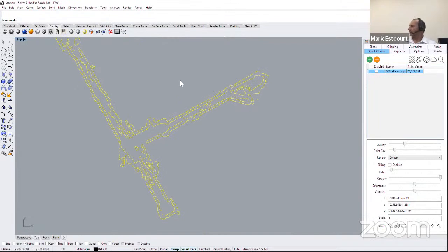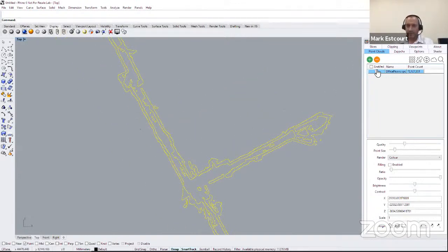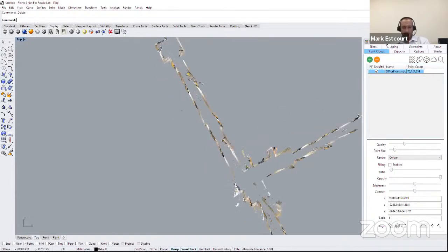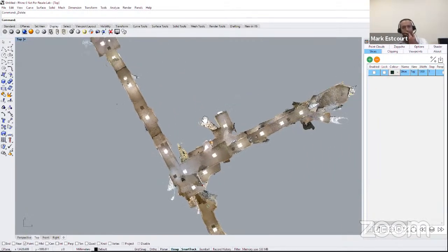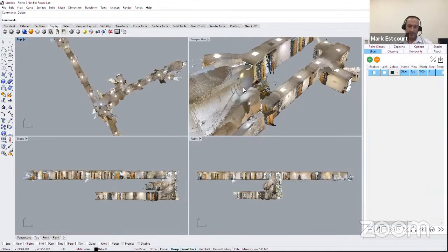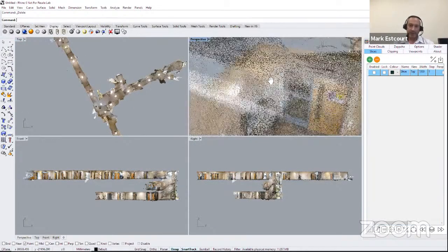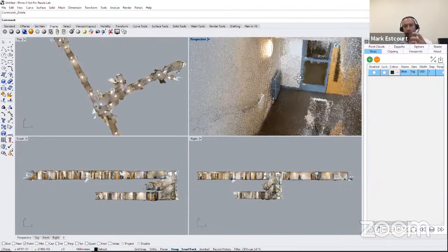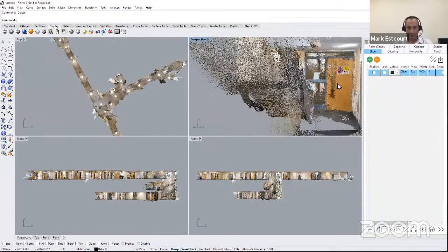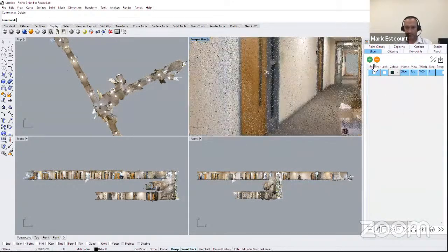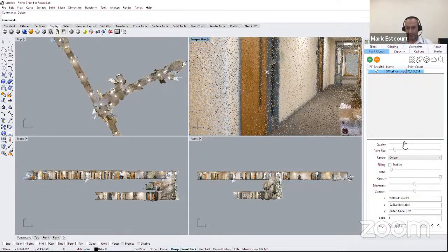Is it worth having a quick look inside the building with the point clouds on? Get to see what the point cloud capture actually looks like. Because what I'm thinking with this as a use case is someone's using a point cloud in the office. Somebody could be out in the field or in the building that is currently being reverse engineered, and a new piece of that building needs capturing because it's not currently in the office being used, and someone's seen a hole in the data. You could basically use the iPhone and capture really quickly.